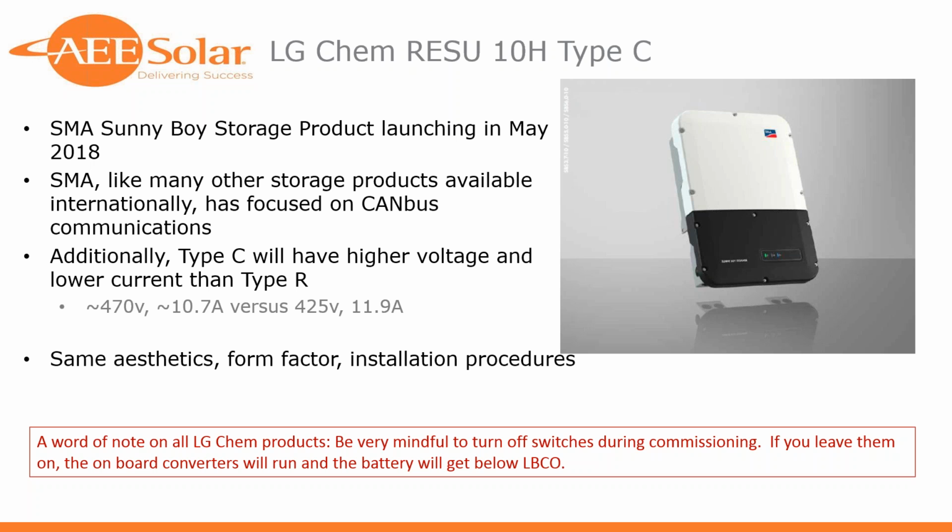So some slight differences in how the units communicate. Unfortunately, they weren't able to do this via jumpers or firmware. It had to be a manufacturing difference. So I want to call it out again: these batteries are not cross-compatible. You need to make sure you order the right battery for the right inverter. And I'll show you guys in the part numbers later what you want to look for.